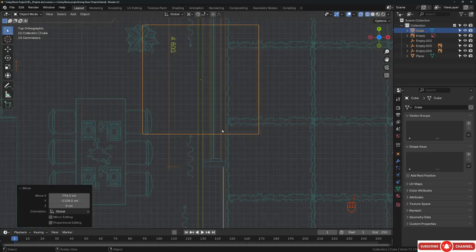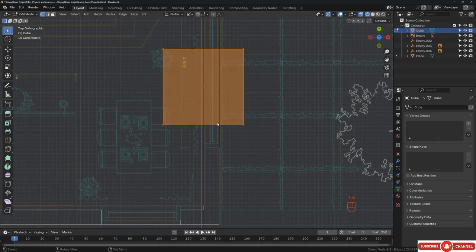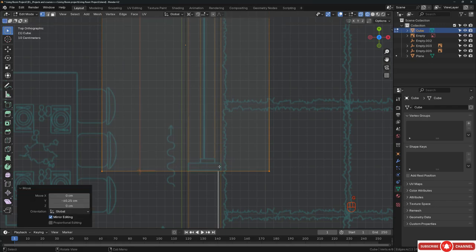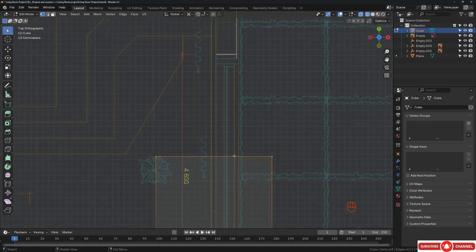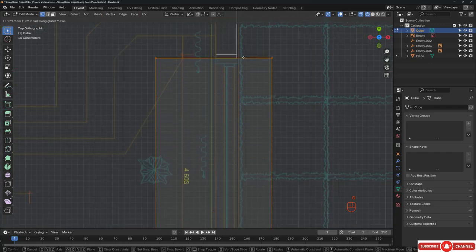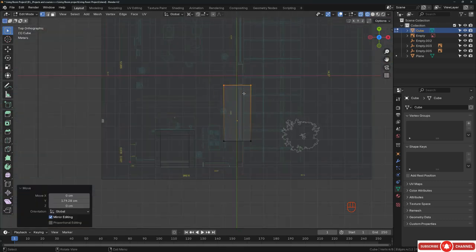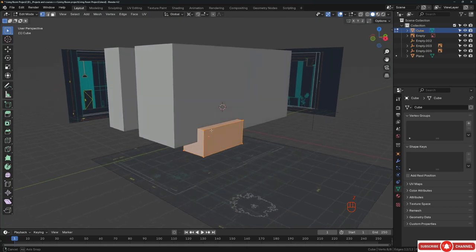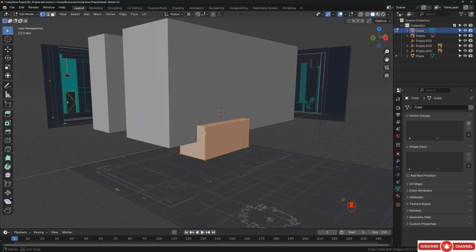You can switch to the wireframe and then hit Tab to go to the edit mode, and I will grab these two vertices and let's align them with the window here, and let's grab those over here, and I will move those right here, I guess, something like that. Let's start with this, and after that just determine the height.